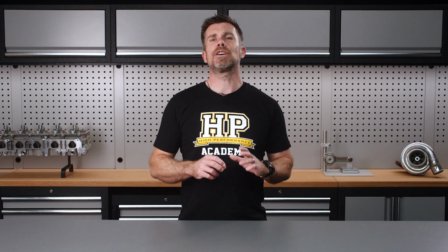If we strip away all of the advanced features of modern ECUs, really the two key elements the ECU is in charge of are supplying the fuel and ignition to the engine. These are the two aspects that we as tuners need to control to be able to make the engine produce good power reliably. We're now going to look at tuning each of these elements separately, starting with the ignition.